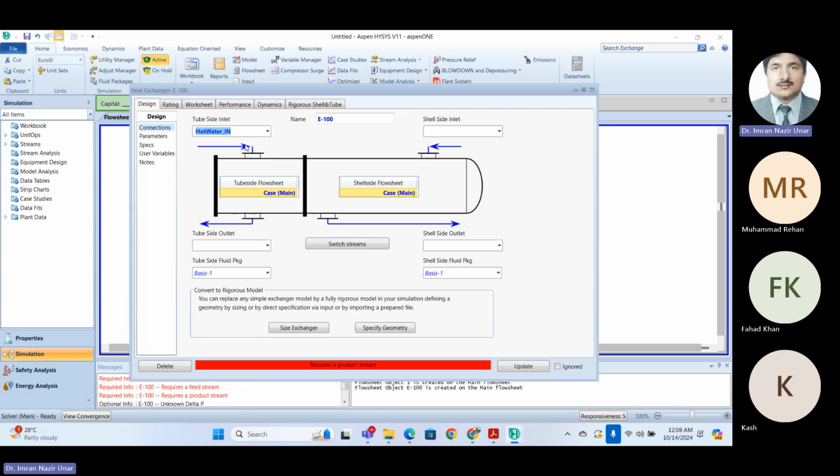So it's better to have a problem with only one metal, the tube, and the tube can be replaced. But if we put the hot side in the shell, then it will also erode or corrode the tube's outer surface and also the shell's inside surface. This is one general heuristic, and we have also done it in the same way.